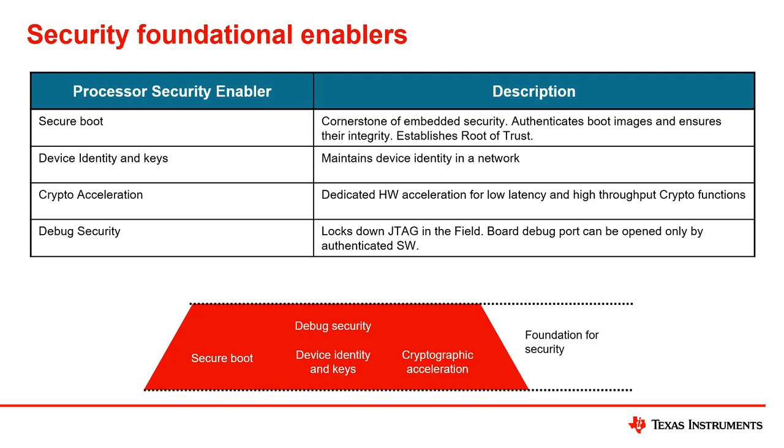Secure Boot is really making sure that your system is going to run code that it was designed to run, and make sure that it can't run other code that someone might try to inject in the system. Really guaranteeing the integrity of the system from a software and a hardware perspective, and establishing root of trust for the rest of the software that's going to run on the system.